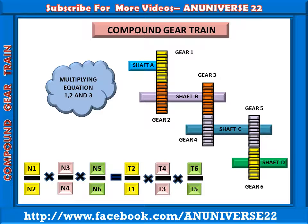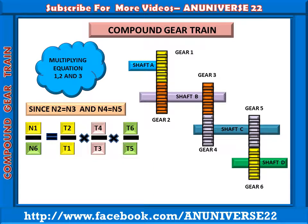So here we can see gear 2 and gear 3 both are mounted on the same shaft, and gear 4 and gear 5 are mounted on the same shaft. So N2 equal to N3 and N4 equal to N5, because the same speed is transmitted from gear 2 to gear 3 and gear 4 to gear 5. Since N2 equal to N3 and N4 equal to N5, we can cancel out N2 with N3 and N4 with N5. Then finally we get N1 upon N6 equal to T2 upon T1 into T4 upon T3 into T6 upon T5.